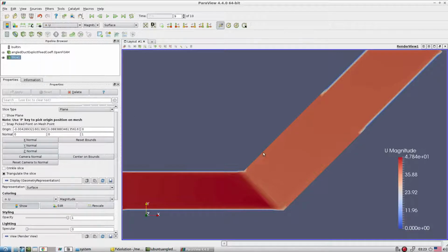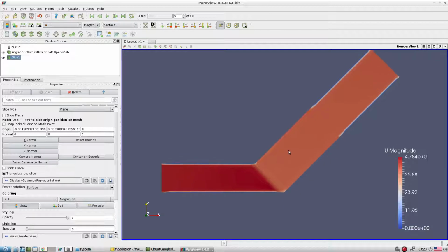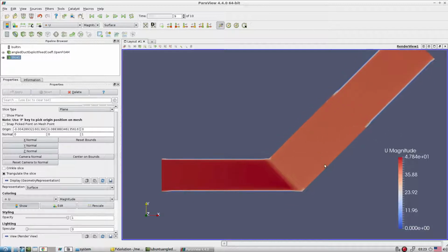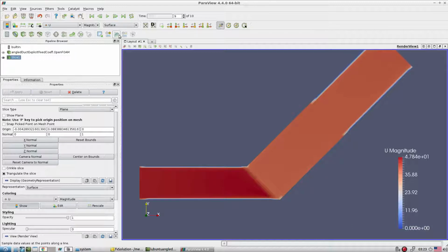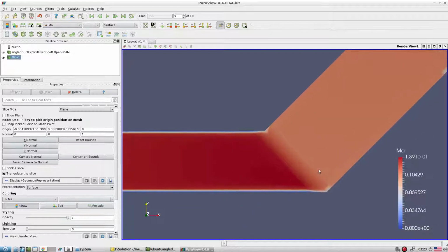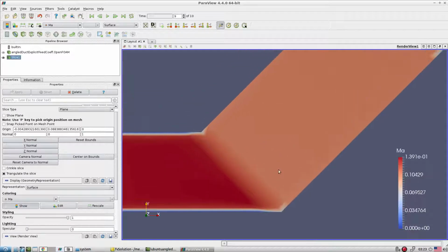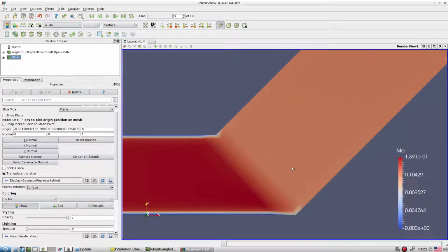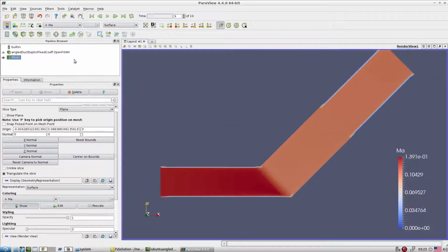So it's not always the case that when we work with compressible flow, we always have to think about the shock and everything. In this class of case, even though the flow is compressible, the shock formation is not going to happen. Why? Because if you look at the Mach number, it's hardly anything, so very low Mach number flows. But our fluid is compressible, that's why we are working with the compressible class of the solver. So this is what we see from here.